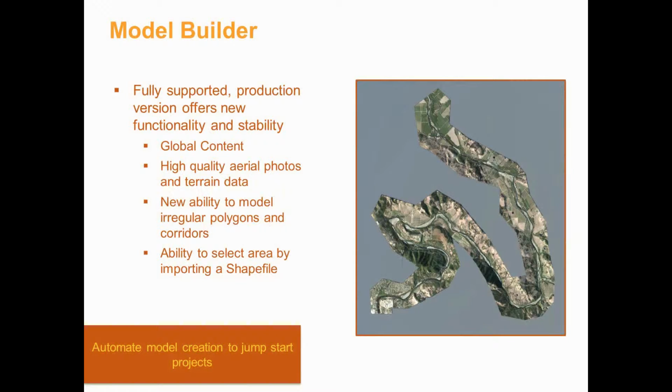So first off, Model Builder, which was technically a technology preview in previous versions, is now a standard feature, which is really nice. It allows you to quickly assemble a model without having to go out and take the time to collect the various bits of data. So it'll utilize USGS servers, city, county, and statewide servers that are available to you to generate terrain, imagery, GIS road design data, building information, water bodies, things like that. So it's nice to be able to have that